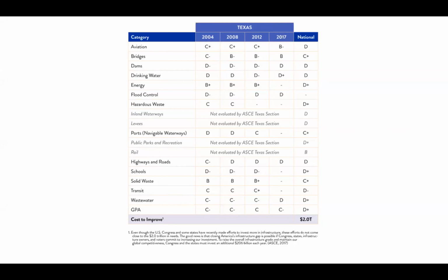The next one is, how do we categorize the intensity of cracks? So I showed tables basically indicating the width of the cracks. And so it could be anything from hairline to what could be severe, which would be something on the order of maybe a quarter or half an inch or even bigger. So it's generally done based on width for cracks. They're flagged, and then there could be additional follow-up and in-depth inspection if needed, if there was a concern about structural integrity from those cracks.